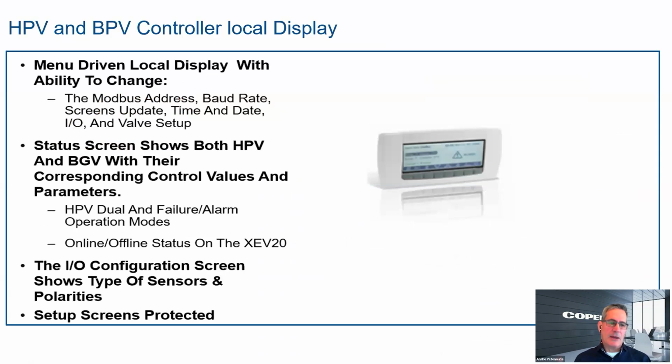And I mentioned you can set up the high pressure bypass valve using the Visiograph. Maybe not a great picture of the Visiograph here, but it's menu driven, and you can set all those parameters there. If you are hooked up to the E3 and communicating the iPro to the E3, you can only view through here. You can't make adjustments anymore. The adjustments have to be done through the E3. So a little bit different setup, but it's there to help.